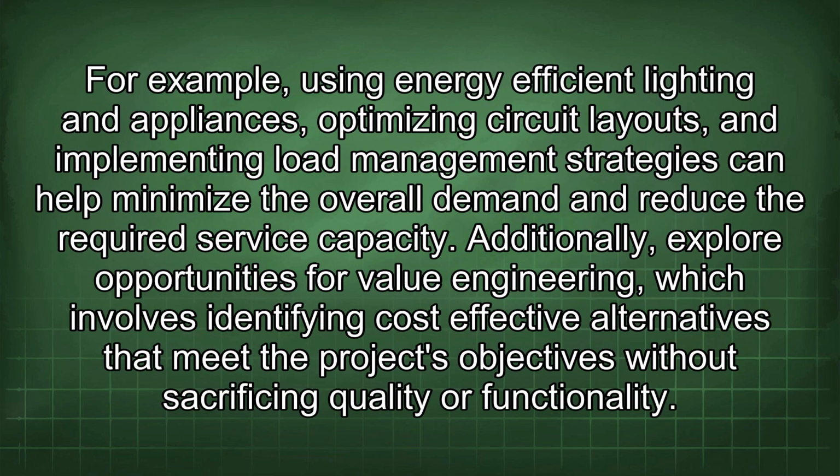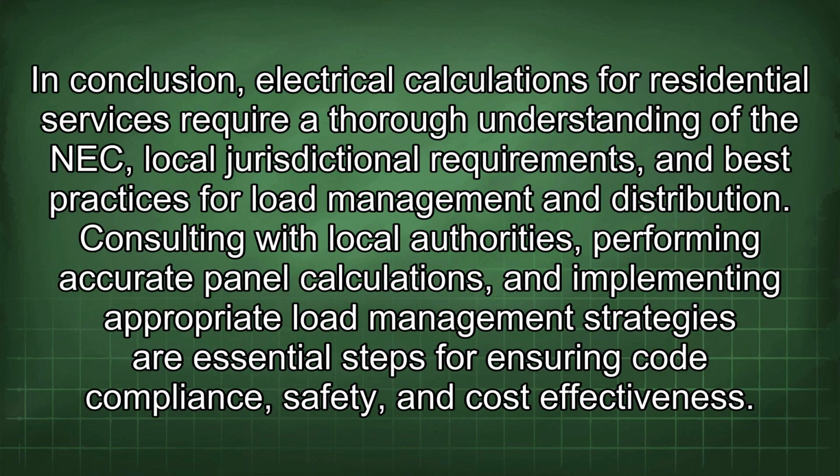Offer suggestions for optimizing the electrical design to reduce costs without compromising performance or safety. For example, using energy-efficient lighting and appliances, optimizing circuit layouts, and implementing load management strategies can help minimize the overall demand and reduce the required service capacity. Additionally, explore opportunities for value engineering, which involves identifying cost-effective alternatives that meet the project's objectives without sacrificing quality or functionality.